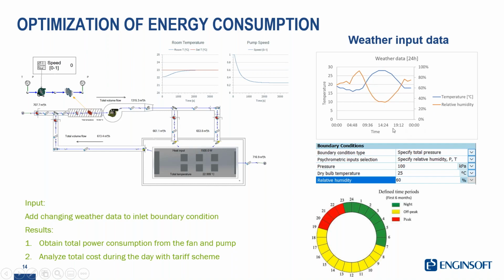to understand what the energy consumption is, because you have different heat exchange due to the external ambient condition, and so in the different parts of the day you are able to have a different energy consumption, and you have a global calculation of the energy that is consumed by the pump and then by the fan of the blower to have the room controlled at the level of the temperature.